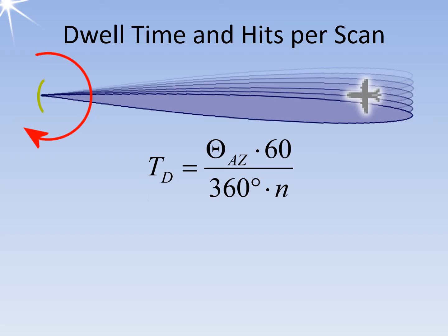The target is, therefore, hit by several transmission pulses. The hit number, m, indicates how many echo signals are generated per target during each antenna slew, or rotation. For example, for an all-around search radar, the hit number represents the number of echoes per antenna rotation. The number of hits per scan is determined by the dwell time and the pulse repetition period.